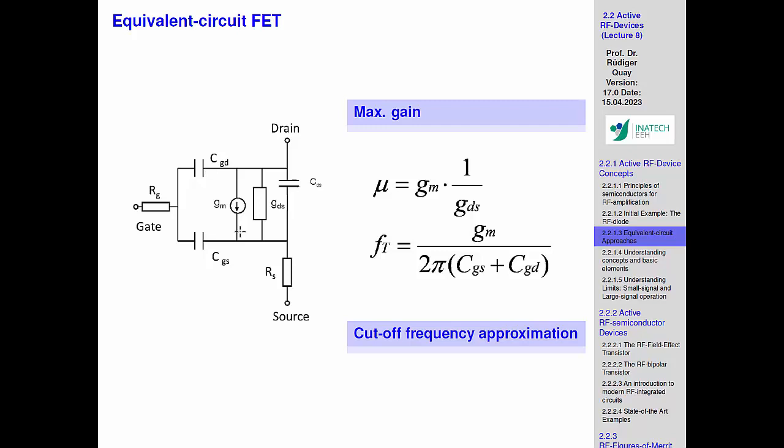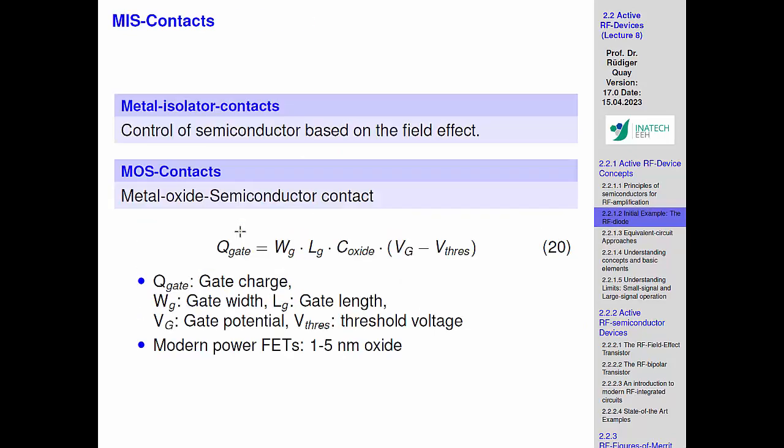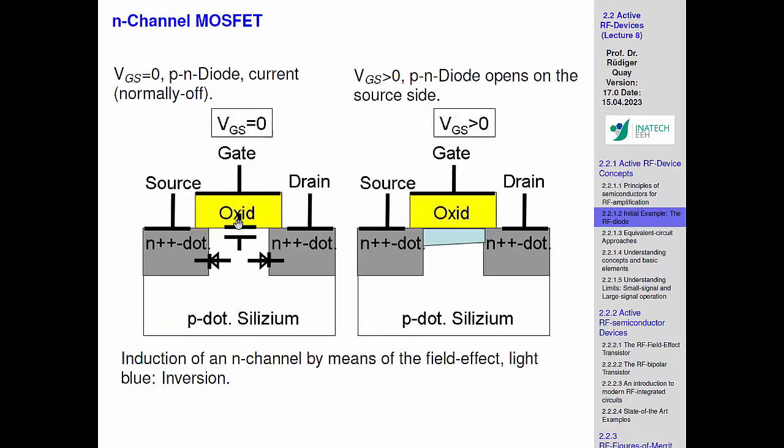But fundamentally understand why people have, apart from making the devices so small for area reasons, done this scaling. Why do people cut this capacitance? Yeah? So the control aspect, this is the forward current component which you need, but this capacitance kills you if you're not serious. But then you have an answer because Gordon Moore said, let's make these transistors small, and the idea was, okay, let's make this small. So we keep the carriers close, but we also reduce the length of the channel.